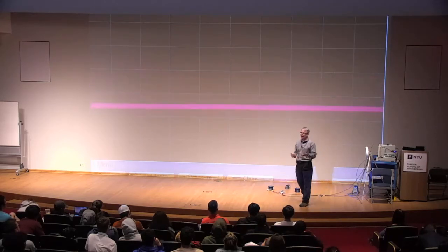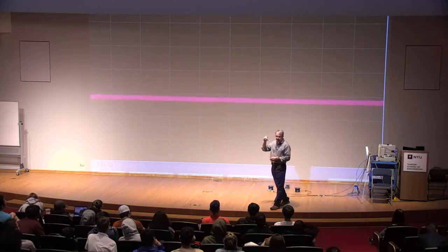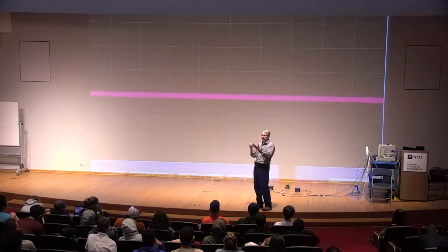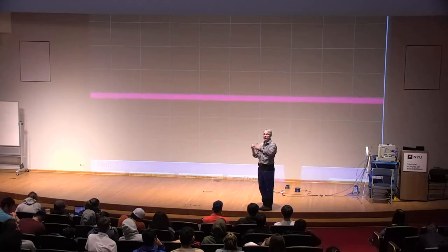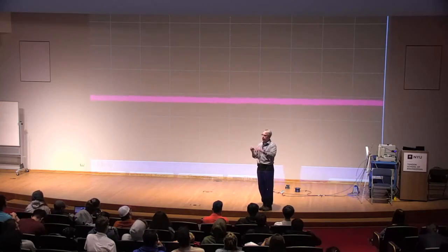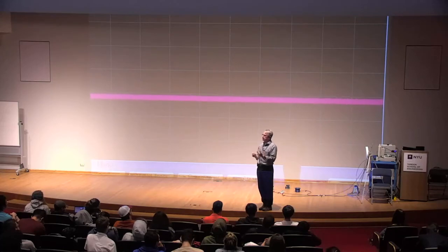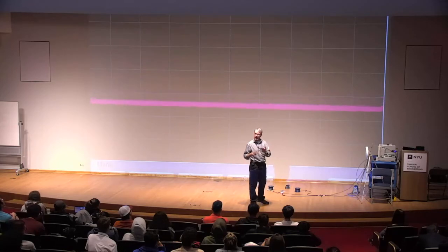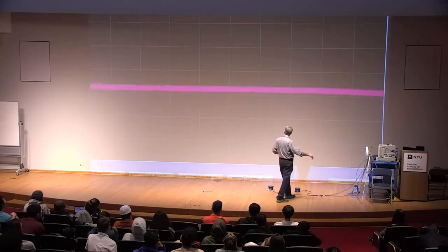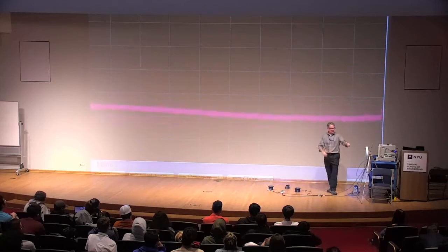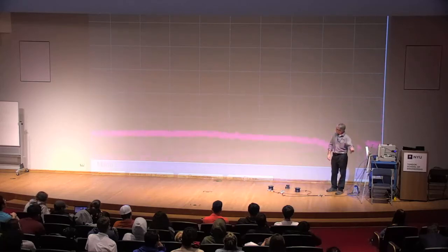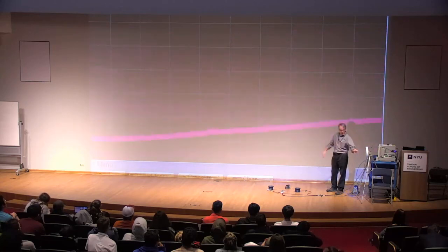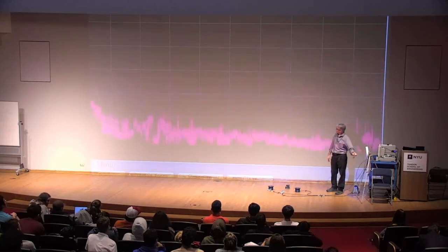So here was the question about the keys. Can your keys communicate? Obviously they can communicate, you can hear them, right? I can have them transmit, in this case, sound pressure waves. So it's still a sinusoidal waveform, and you can hear that. But I'm more interested, from an electronics point of view, in how I do this wirelessly. So this is where I'm going to go into what's called a backscatter mode. I'm just going to jingle the keys in front of the transmitter, and I'm going to receive it off the same one, and you can see some pretty fast changes here. That doesn't look like data, but if I was to jingle them at a certain rate, I could represent ones and zeros as I do this.